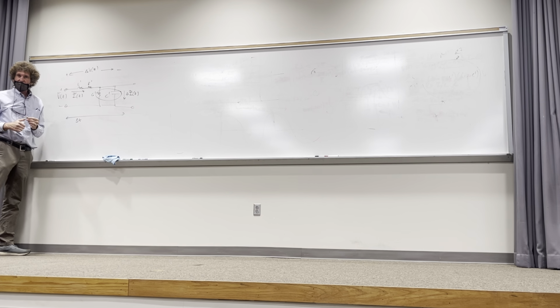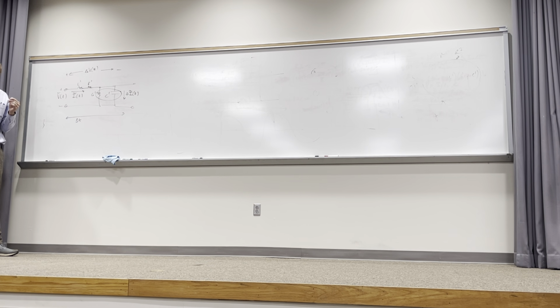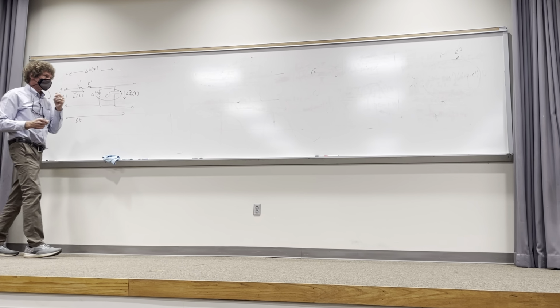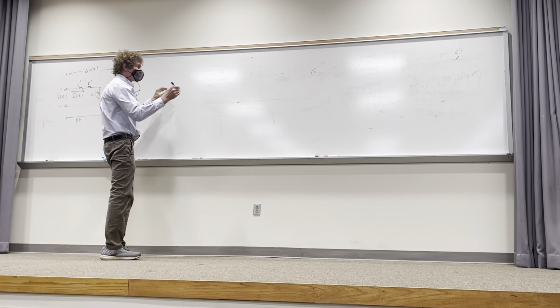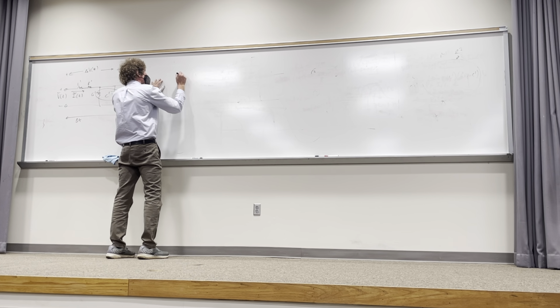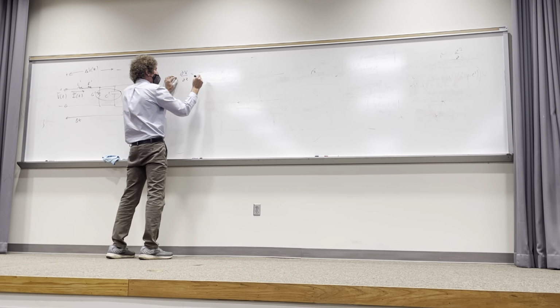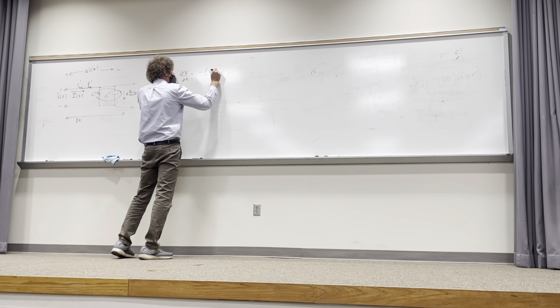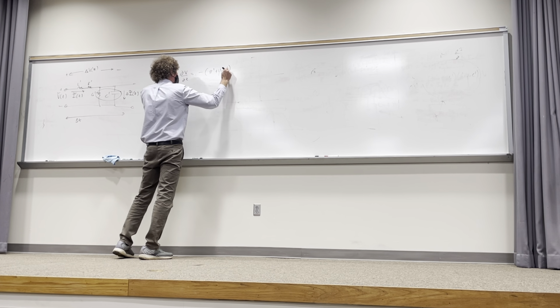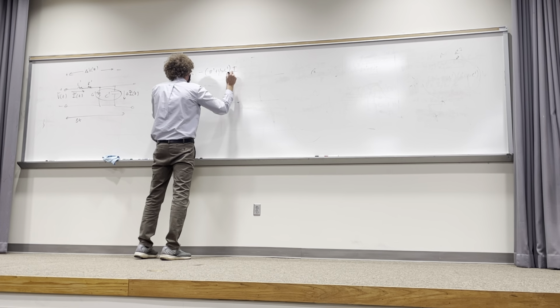Now this is what I set up last time, and I told you the reasons for the development. All these things are the primes, they mean per meter values of capacitance, inductance, resistance, and conductance. From that, we had two equations we developed. It was dV/dZ is equal to, you can put the minus sign here if you want, minus R prime plus J omega L prime times I.